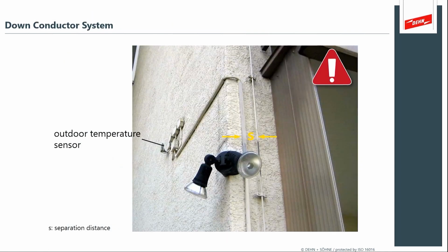And here's a really nice illustration photograph that shows exactly that concept. You have a down conductor that's passing right next to electrical lighting and maybe security sensors, and what you will have is something that looked like that photograph from the other slide, where lightning will attach to your air terminal, which is what you want.